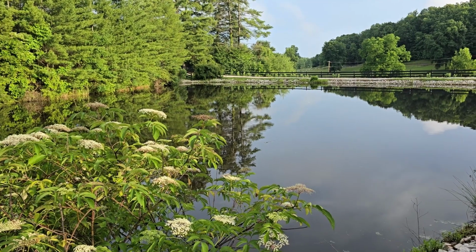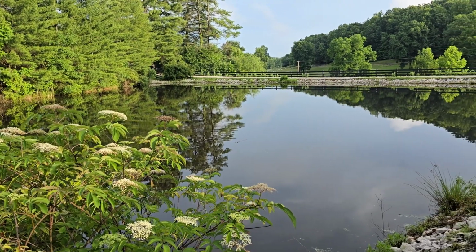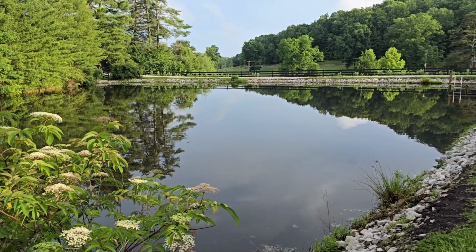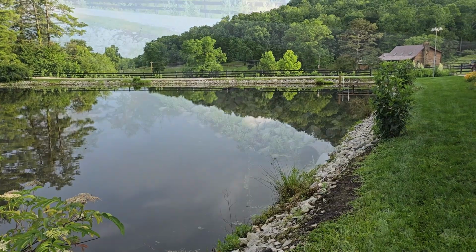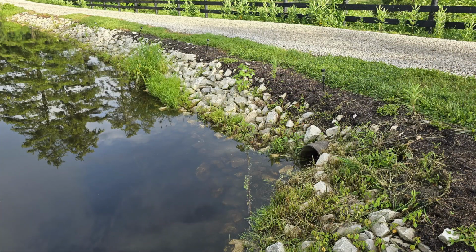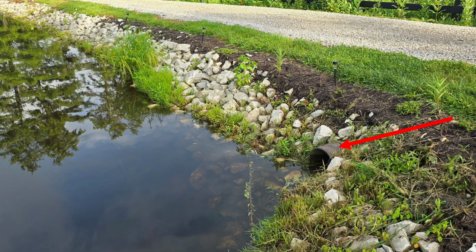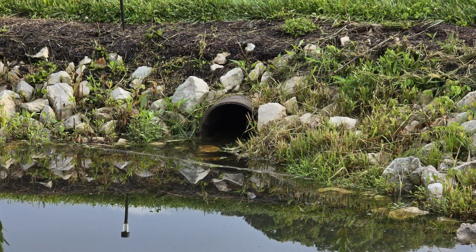Many ponds and wetlands like this one are built without a spillway. Instead, a pipe or a culvert is used to carry water through the dam and not cause erosion. An overflow pipe that carries water through the dam can be difficult to find. The entrance to an overflow pipe must be kept clean of debris. If the entrance of the pipe becomes blocked, water can flow over the dam and wash out the dam during a flood.